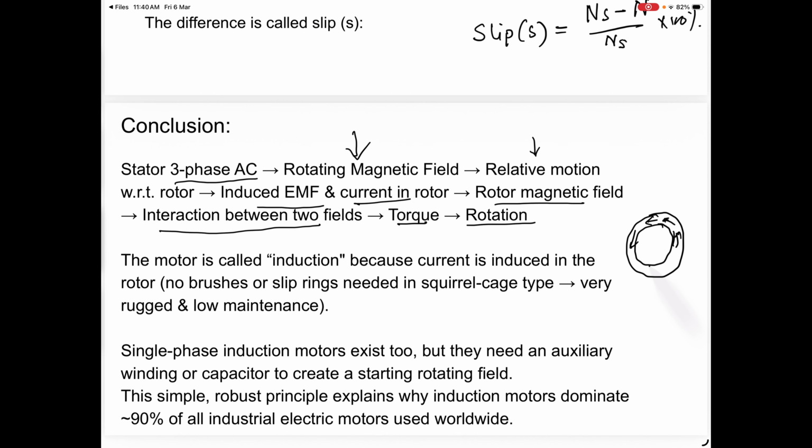The rotating magnetic field is there. And due to this field, the rotor bar conductor present over here moves. So in the rotating magnetic field, because the flux is changing, EMF is induced in the rotor conductor, and as it is shorted, current starts flowing.